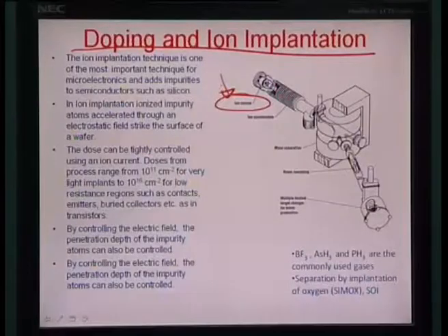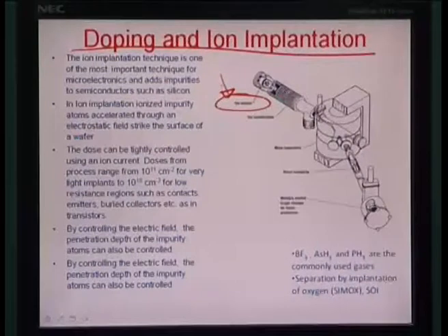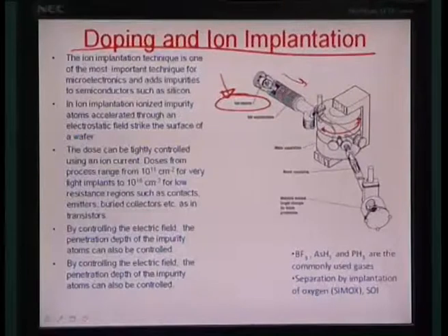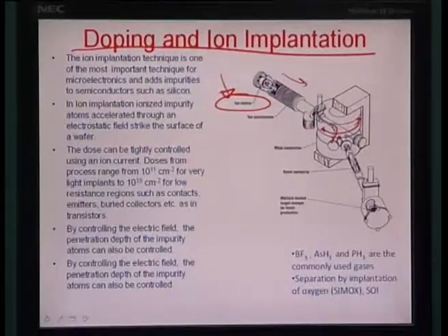So how you do the deep doping is essentially through using something called an ion implanter. Here there is an ion source which can generate from a gas phase a beam of ions, positive ions typically, and then they are accelerated through an electric field, and it reaches this magnetic coil here, which can, based on Lorentz forces, deviate the ions into different tracks.